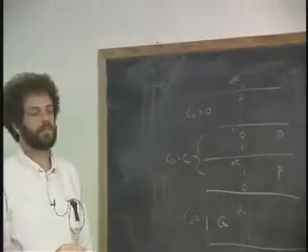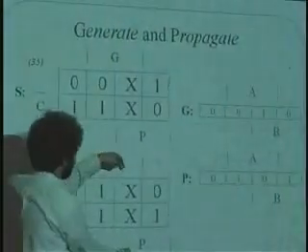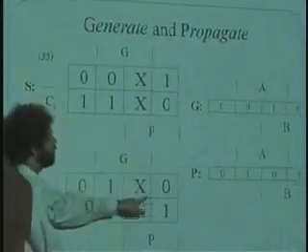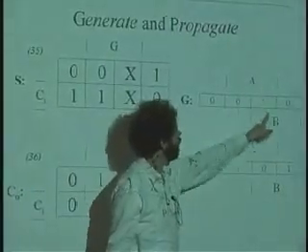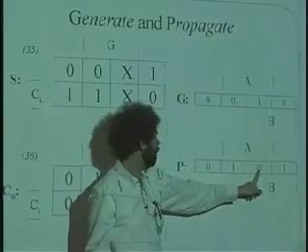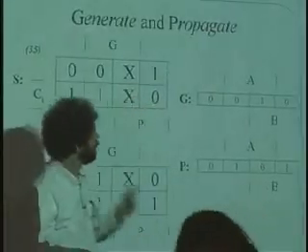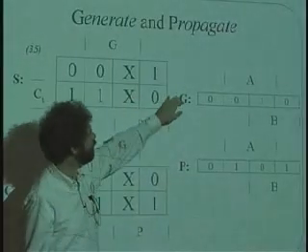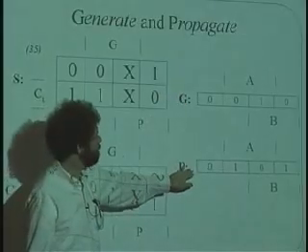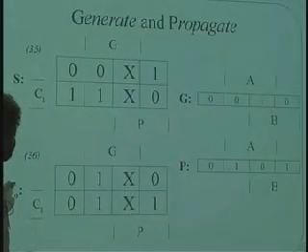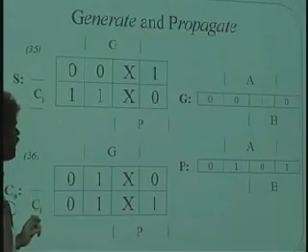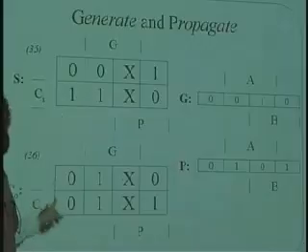Great. Nice. So it will not be the case that generate and propagate are ever on at the same time, and that's the reason for the x's here, because we're saying that in the generate case, when A is high and B is high, we're going to turn the propagate off. So we're going to pre-compute G and P, and then based on G and P, we're then going to compute C sub O as a function of C sub I. And notice that this function is simple.